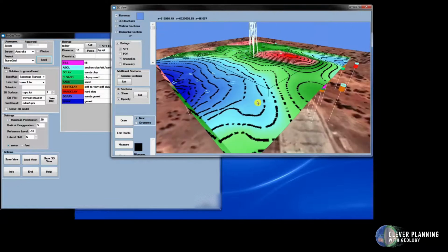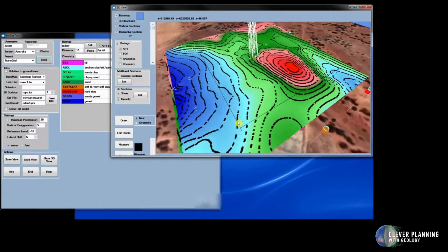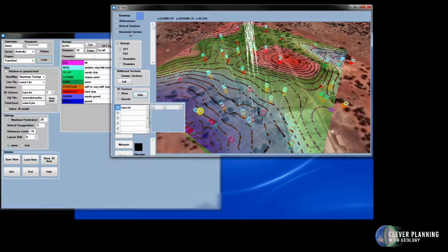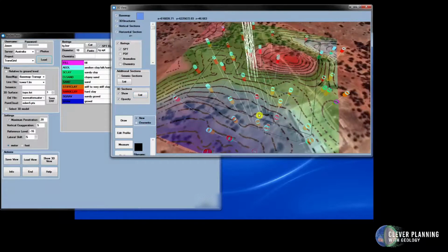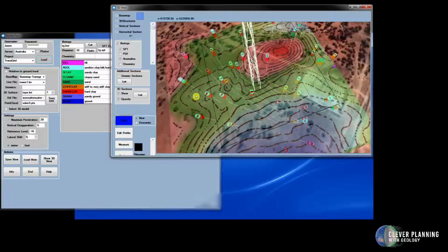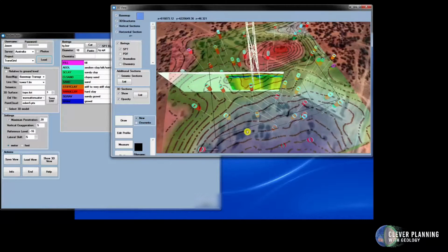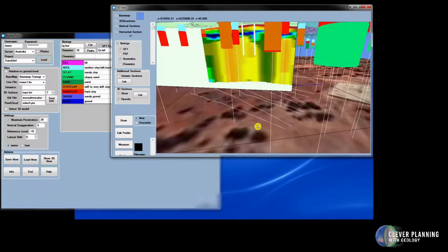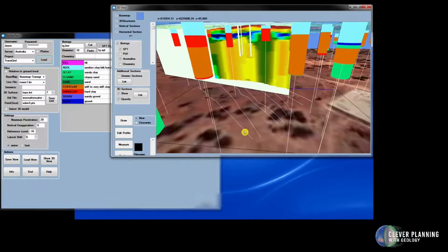This area also highlights another common issue with boreholes. Boreholes, particularly in sediments, are a very coarse sampling technique. They certainly do not produce a facsimile of the ground. As seen in Eden, they often miss key layers if they are not targeted. If we take a cross-section through some of the data, we can see a red layer at the top corresponding to dry wind-blown sands.